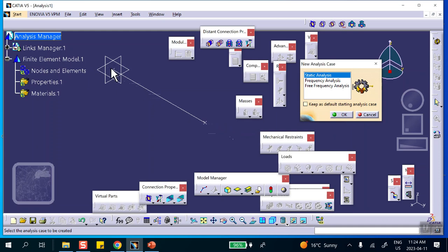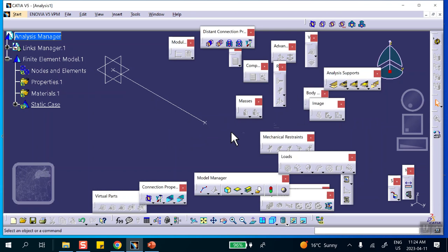So do a static problem. What I should be getting is 10 Newton divided by the stiffness of the spring, which is 4, and you're going to get 2.5 meters of deflection. And this allows me to debug any issues that I might have. So first we do static analysis. Now, instead of meshing this, I'm going to show you what will happen if I don't mesh it.